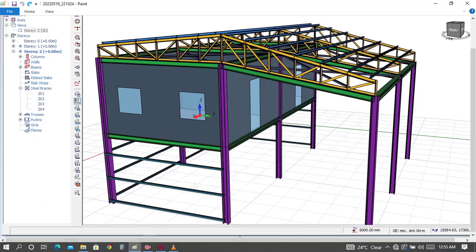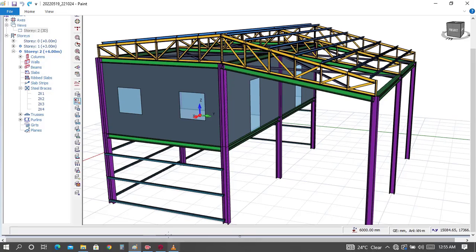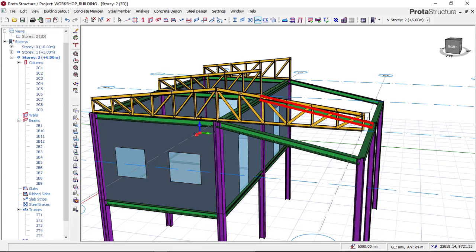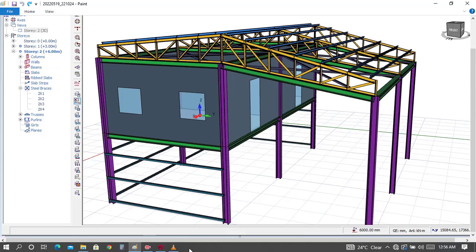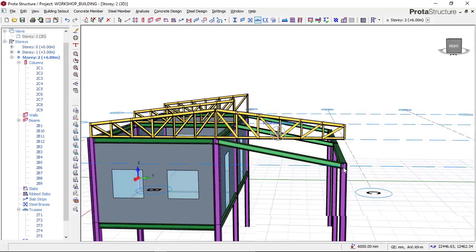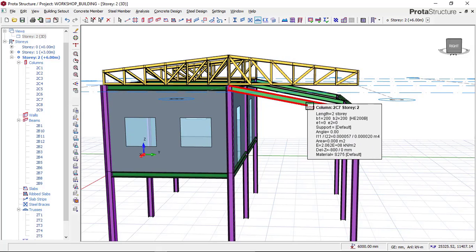Looking at our model, we have this upper side at the same place, but this does not correspond to what we have on the model we want to create. On our model, this truss is flushing with this beam member, and this beam member is inclined with minus 800. But what we have right now is not that. So to do this, we have to drop this end of this truss down by minus 800 so it can flush with this steel beam member.